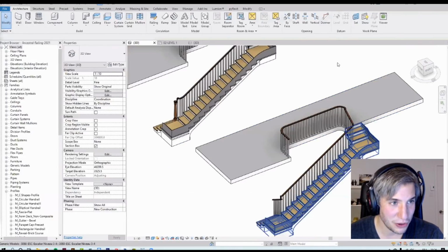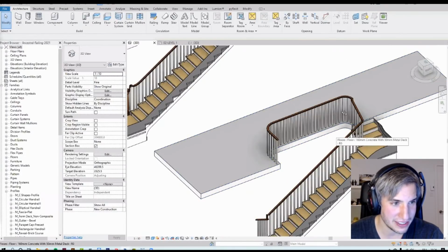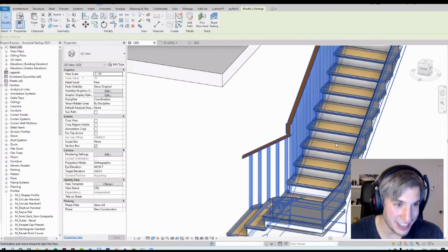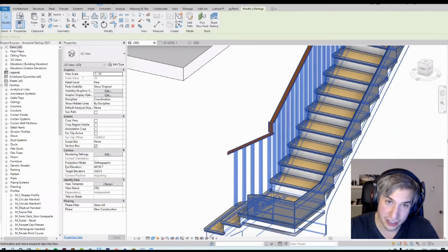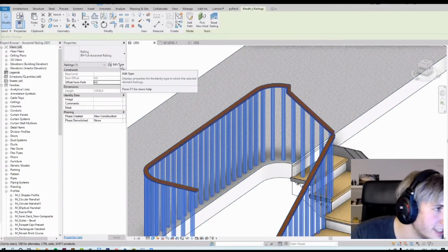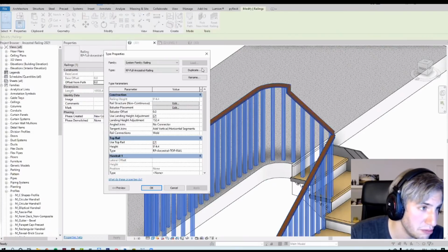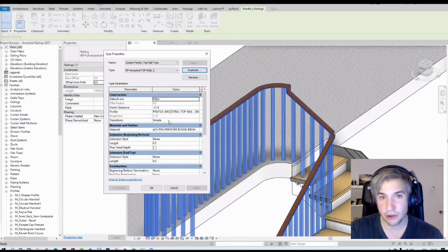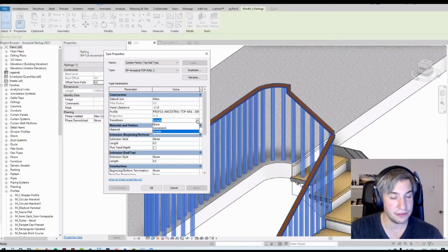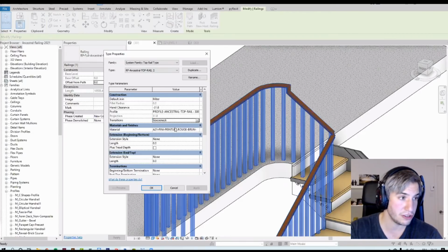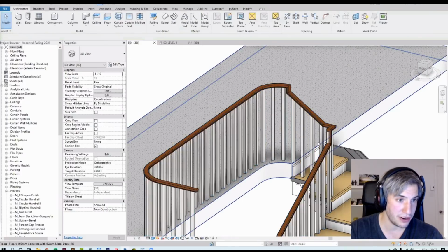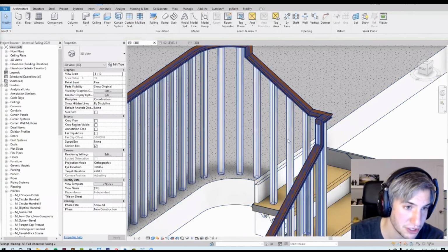And so here you can look, this railing is all wrong. The transitions are not working at all. The first thing that you need to do is the transition style, which right now, I think, is set at simple. So I'm going to duplicate this, change the style, duplicate this again. And the transition, remember we have three styles: none, gooseneck, and simple. So I'm going to use gooseneck here. So already it's much better, although I have some issues with balusters once again.